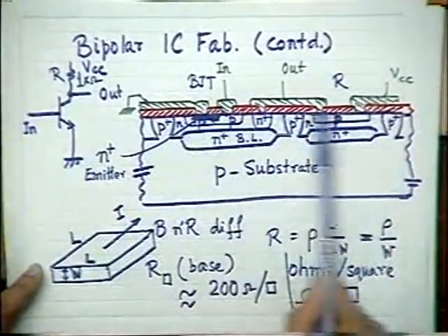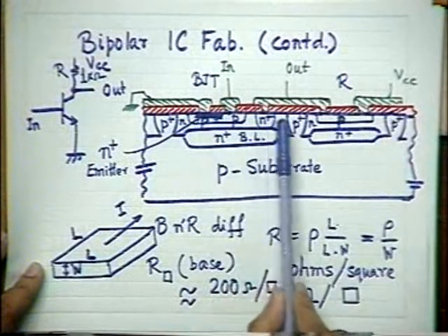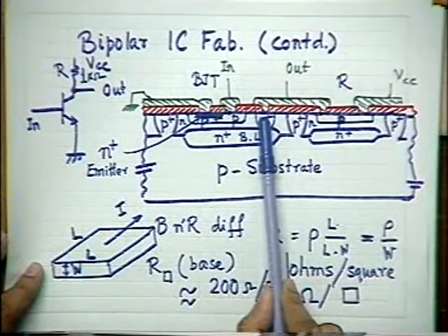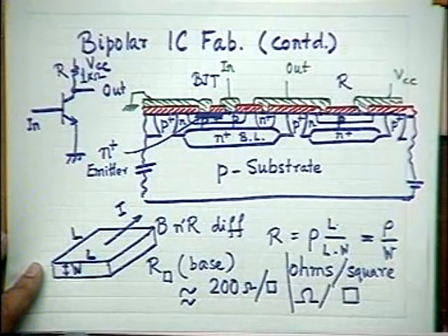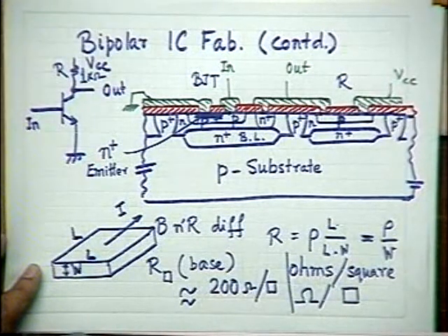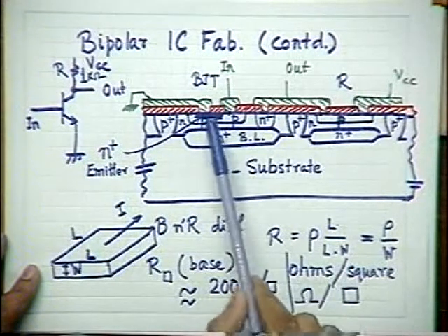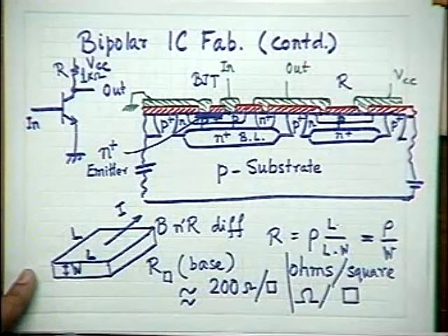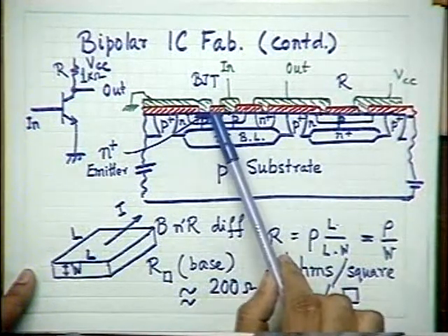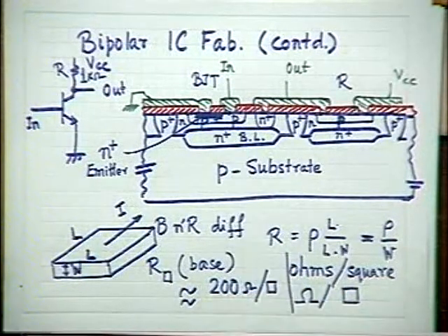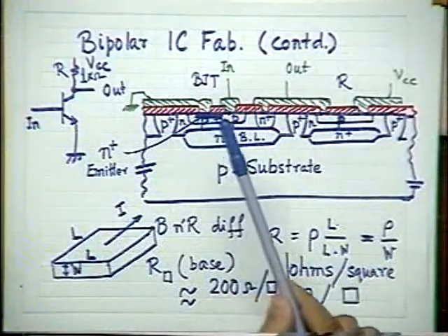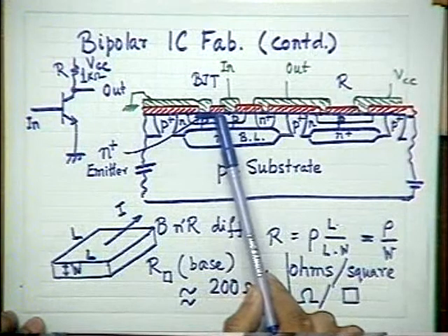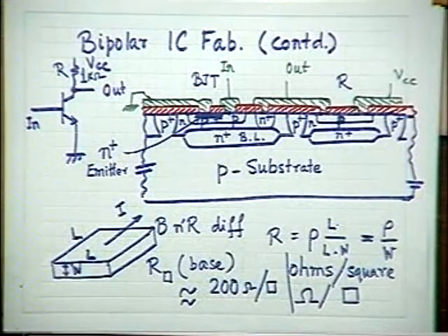You remember, of all the doped layers, it is the emitter and the collector contact region which are most highly doped. Emitter, you know, for achieving a very high gain of transistor, one has to achieve a very high injection efficiency of the emitter base junction. And for that, what we do? We maintain a very high emitter doping compared to base. That is a fundamental requirement of a good bipolar transistor. Because our emitter doping is very high and it is the last doping, its sheet resistance is usually quite small. What is the order of emitter sheet resistance? Even less than 10 ohms per square.